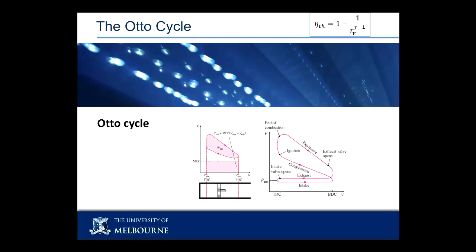Those are the tools and the rules that we use to move our way around. The Otto cycle and the diesel cycle we use ideal gas for. So usually to solve these problems we're using PV equals RT, and any other rules that we've developed for ideal gases, like the temperature ratio connecting to the volume ratio for an isentropic compression.